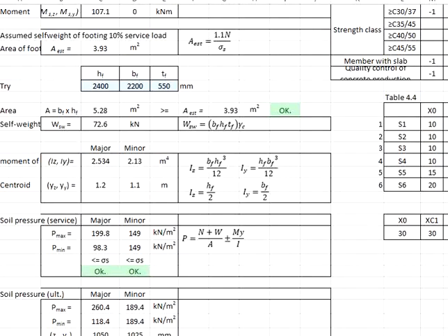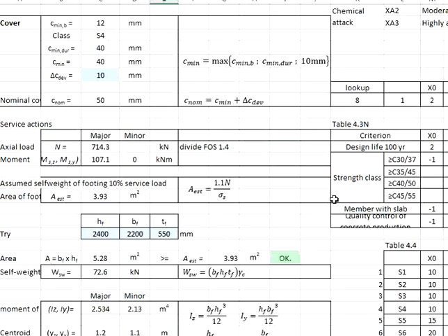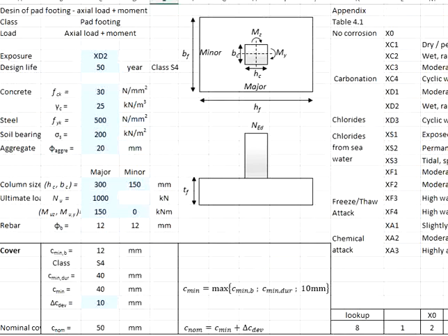Otherwise, no matter how strong you make the structure, if the soil bearing capacity is exceeded, the foundations will undergo settlement. Eventually, this is going to jeopardize the integrity of the entire structure, resulting in the structure failing.